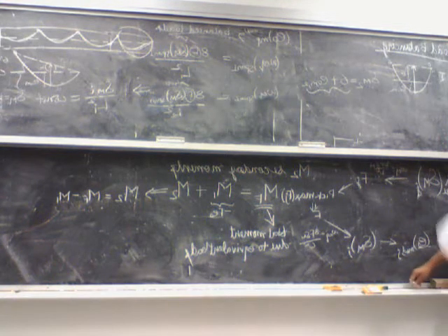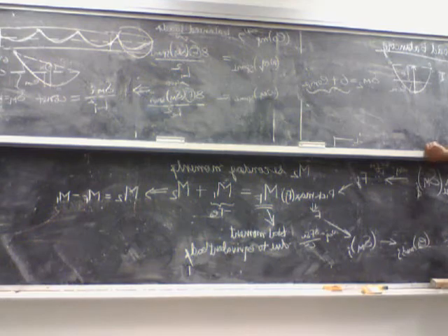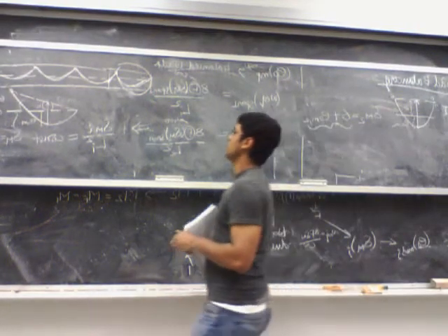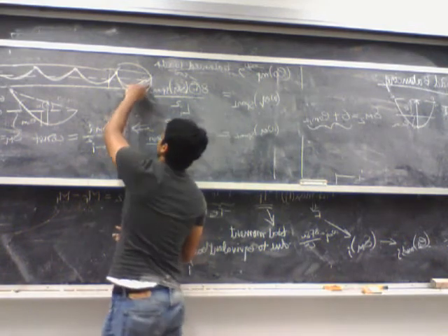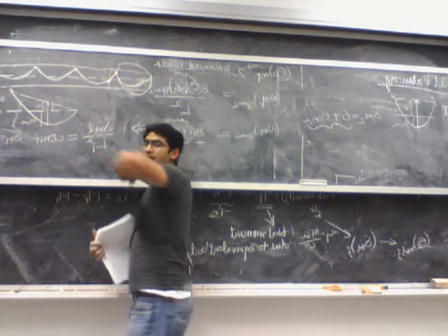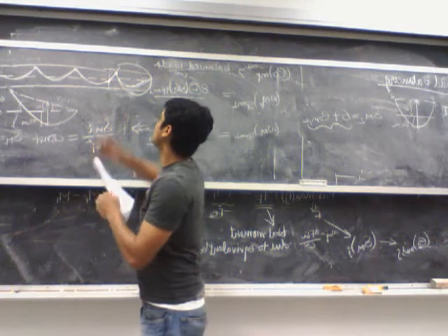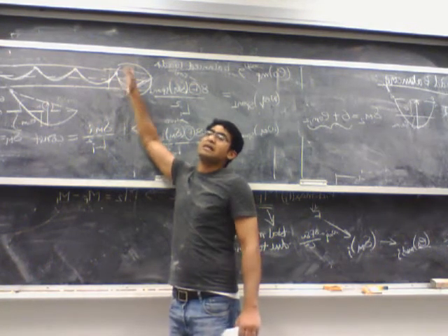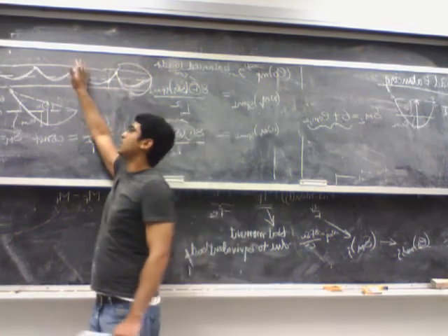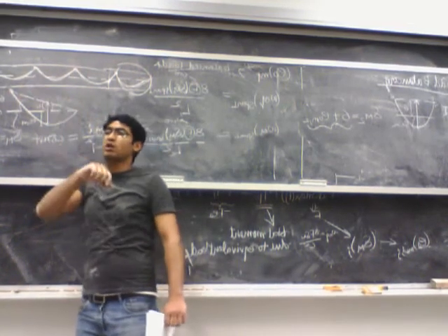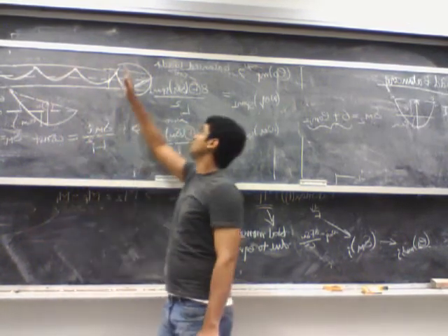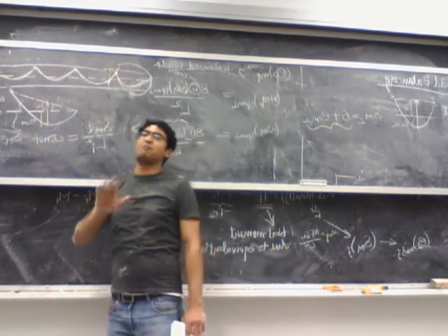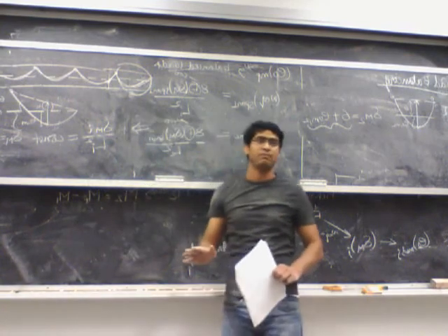Yeah. So what Anthony is suggesting is that one thing you also need to account for is that, at least in the end span, the maximum moment doesn't occur at the mid span. It might not even occur at the mid span for the other spans, depending on what loads you are trying to balance. But unless your loads are pretty weird, at least for the end span, the maximum moment will not occur at the mid span.